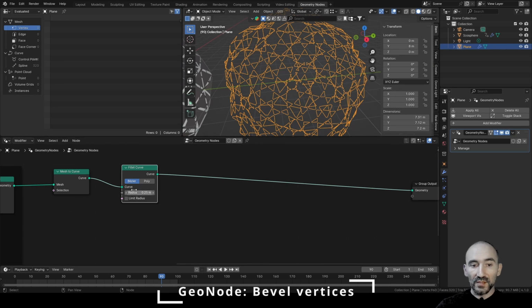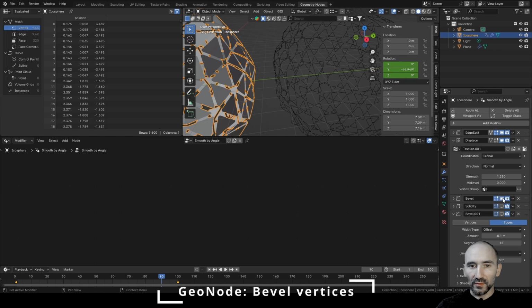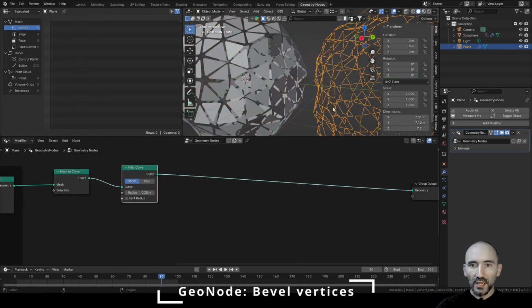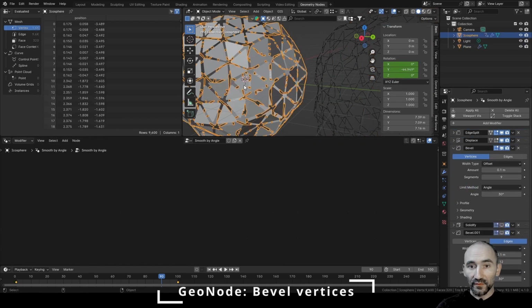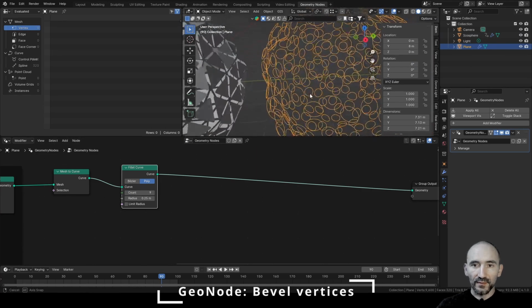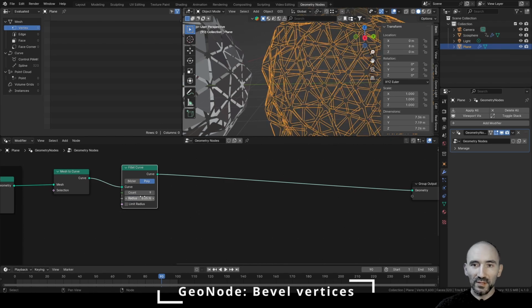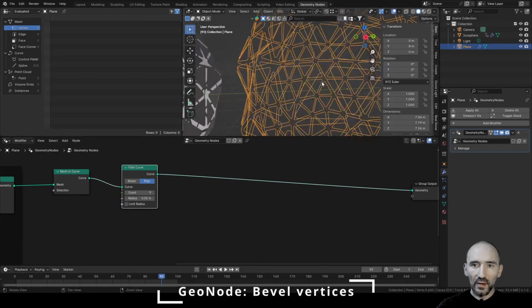So we need to decrease to have a similar result to this sphere if I enable this bevel on the vertices. For example, we can select poly, and set the amount equal to the value of the modifier of the first object, so 9 segments. And instead of using an amount of 0.1, we can select our mesh and here set 9. As you can see, the fillet value is too much, this radius. So we can set 0.05 to have a similar effect on our curves.